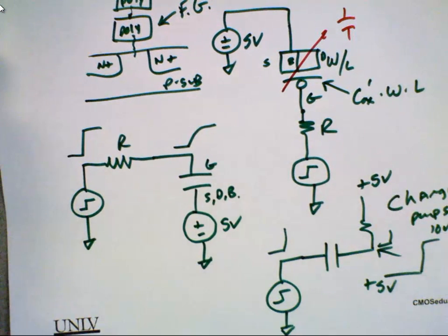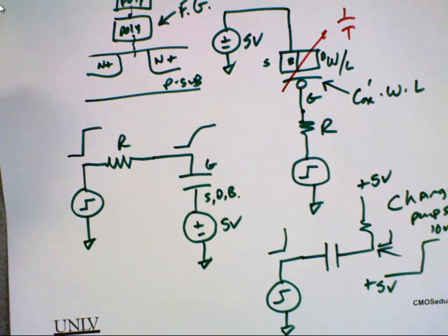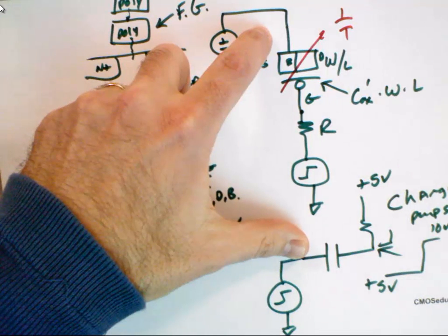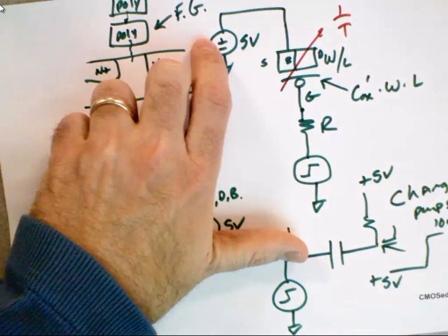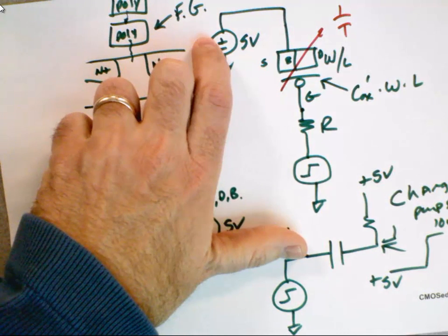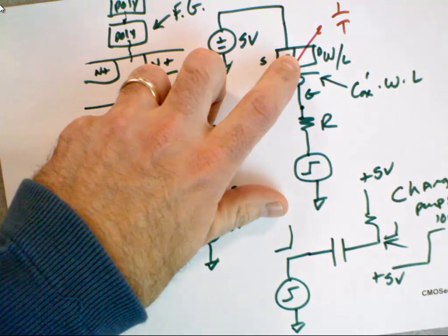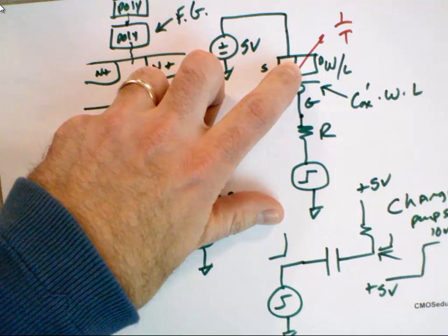All right, any questions before we move on? The whole point of this was I put that homework problem and I said, oh, we got 5 volts here, and then I thought I've got to make sure in class I cover that, because they may think this actually matters. It doesn't matter for the step response. It matters for keeping this in strong inversion. And again, I'm going to cover that more in a moment. We'll review the NMOS and we'll do the PMOS.